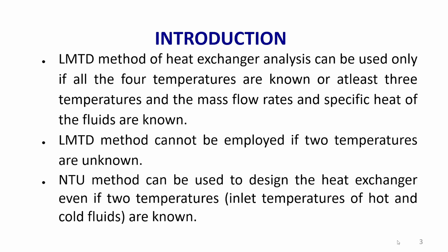If the fluid used is either water or air, even if Cp is not specifically given, we can take the standard values. Cp of water is 4.18 kilojoule per kg Kelvin and Cp of air is 1.005 kilojoule per kg Kelvin. But if the mass flow rate is not given for either the hot fluid or cold fluid, then we will not be able to find the value of Q. Once we know the value of Q, and the other fluid's mass flow rate as well as one temperature, we can find the unknown temperature.